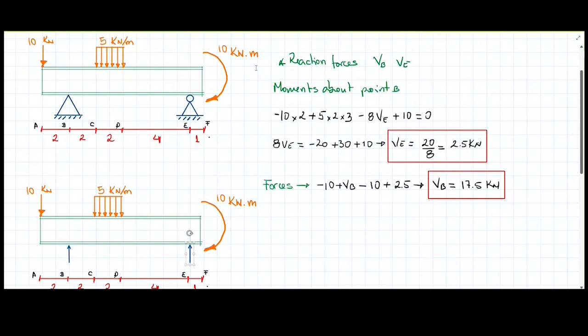It might be that this moment is going to induce some sort of actual force on this. I don't know because we need to construct the free body diagram to account for that. However, in this case, it's going to be pretty small, and then we are not considering it here. In this roller, there is not going to be any actual force generated as a consequence of a reaction because this beam is free to expand, let's put it in that way, in the horizontal direction.